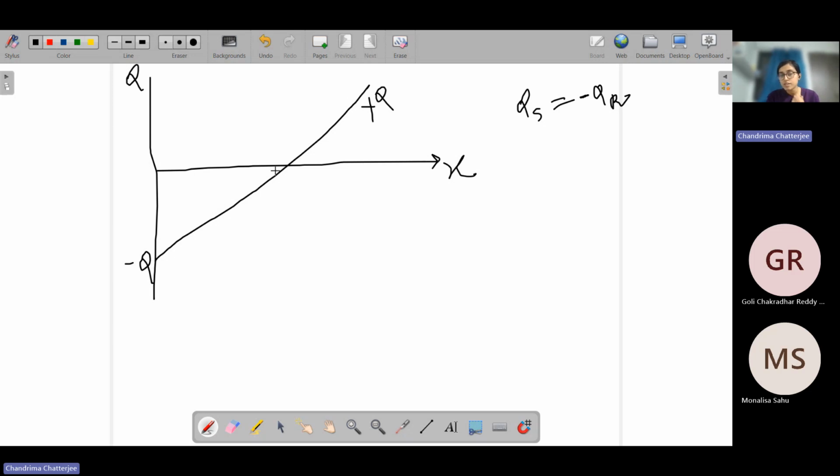In the lecture also, sir has explained that. So this is the midpoint. This is basically 0 point. This is L, and this is x equal to L by 2. So at this point, you will always get the reactive power is 0. And if you also calculate it, putting x equal to L by 2, then also you will get Q comes out to be 0. Did you understand why the answer is 0? Yes, I got it. Okay.